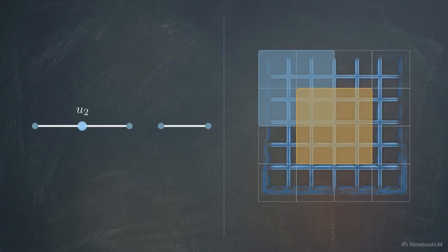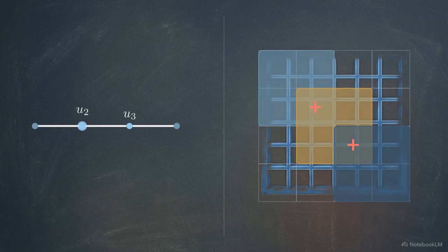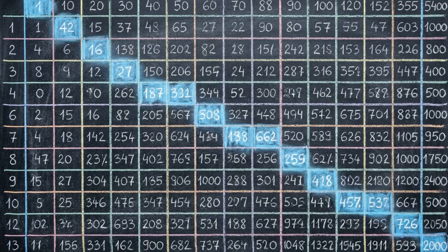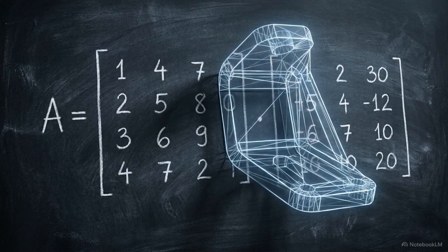When we drop their local matrices into the global grid, they overlap directly in the cell corresponding to that shared coordinate. This overlap represents addition. We are summing the physical stiffness contributions from both elements at that shared boundary. As the third element snaps into place, its matrix drops in, continuing this overlapping sequence down the diagonal. The completed global matrix now serves as a unified numerical map of the structure, housing every local stiffness contribution and every geometric connection within a single coordinate system.